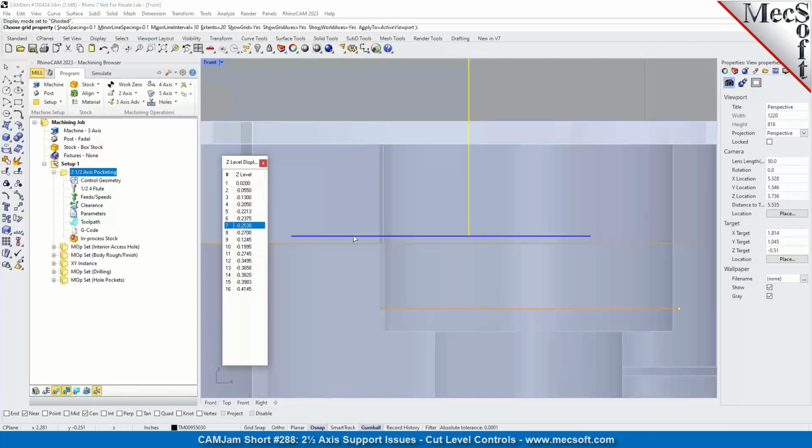You'll see that you had one that was slightly not as deep. This last one's not as deep, like you mentioned, Joe. And if you look at the bottom one, 15 and 16, those are your finish cuts, and you saw we set it to be 0.02, but if you see the difference between 15 and 16, it's not 0.02, it's slightly less than 0.02. So we divided evenly to give us something less than what you've specified in the dialog. Hope that makes sense. Yeah, that's something that needs to be understood.